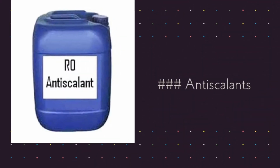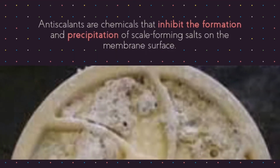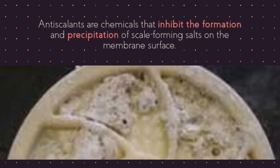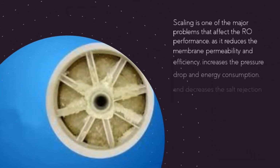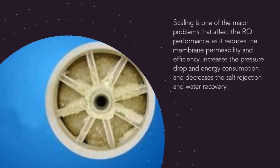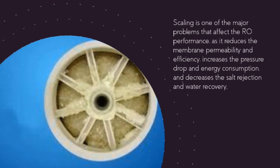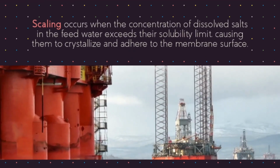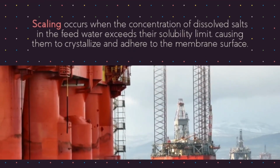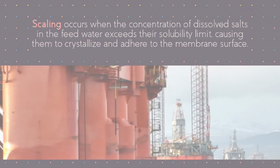Antiscalants. Antiscalants are chemicals that inhibit the formation and precipitation of scale-forming salts on the membrane surface. Scaling is one of the major problems that affect the RO performance, as it reduces the membrane permeability and efficiency, increases the pressure drop and energy consumption, and decreases the salt rejection and water recovery. Scaling occurs when the concentration of dissolved salts in the feed water exceeds their solubility limit, causing them to crystallize and adhere to the membrane surface.